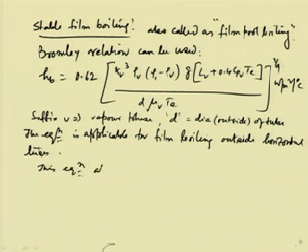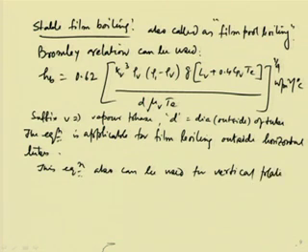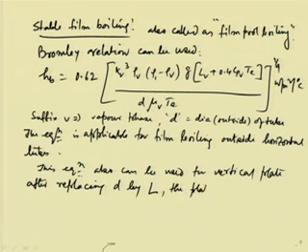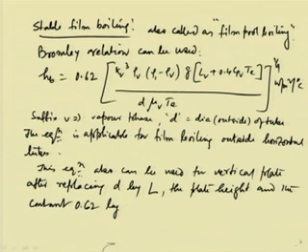and this equation also can be used for vertical plates after replacing d by L, the plate height, and the constant 0.62 by 0.70. Okay. So, this can be done.